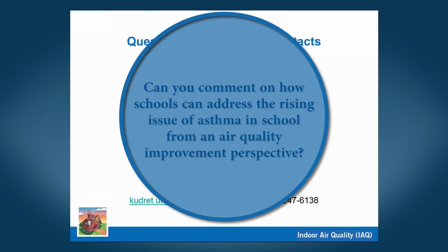A concern I would have is often motors aren't designed to pull or push air through denser mediums, so your energy consumption can go up, and of course your indoor air quality may go down, even though you've put in a denser filter, because you simply can't pull the air through. The system wasn't designed for that.